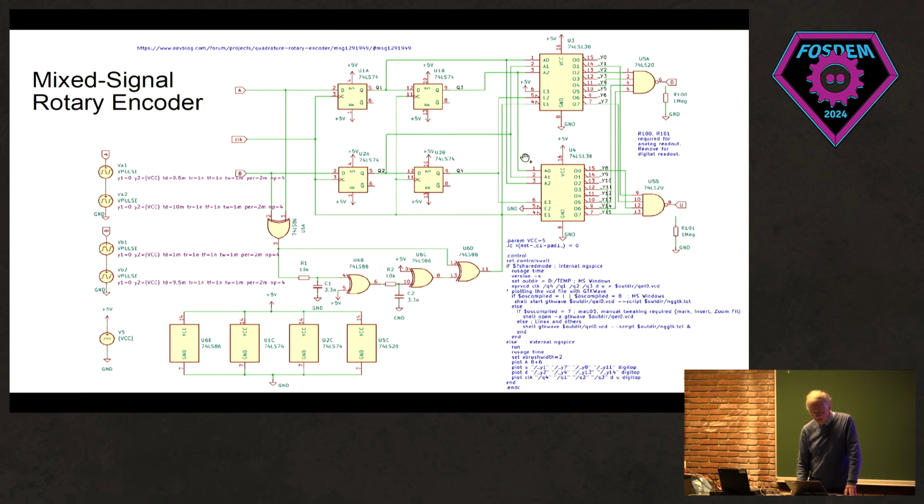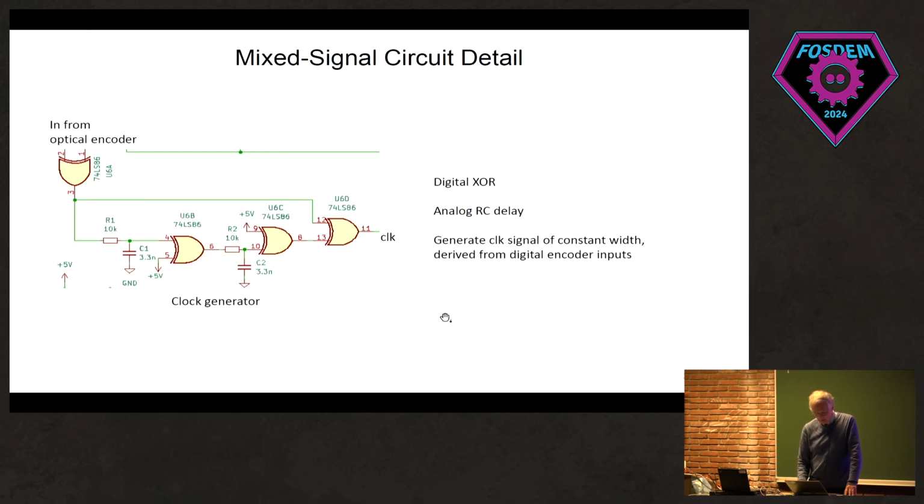Well, this is the venerable 7400 series of devices. You have flip-flops here. You have some output decoders and some NAND gates, and you have some XOR. Oh, no, this is NOR gates. Yeah, and you can simulate this whole thing together. And you see that this is mixed signal means because we're using the digital output here for a delay line. Yeah, so we have an RC delay and another RC delay, and we have the original signal, and so this gives an output pulse of a specific width.